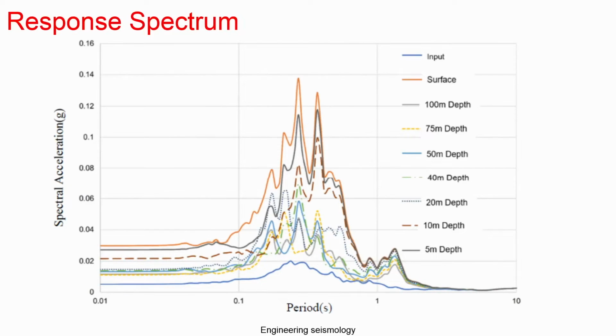Obviously, here also the response you are measuring depends upon where you are measuring. The response will be different, because for the given input you are getting the response, correct. So, this is how you can see a typical response spectrum, which was developed as part of my research to understand how the different layer velocities are getting the response. So, this is actually the input response of the given earthquake, recorded at an engineering bedrock rock site, so this is rock recorded data.